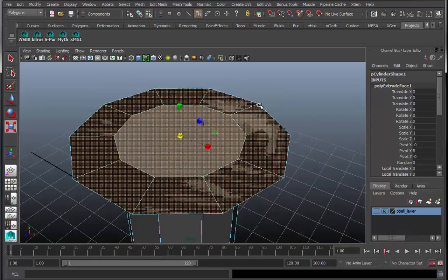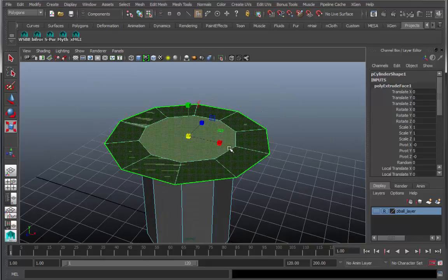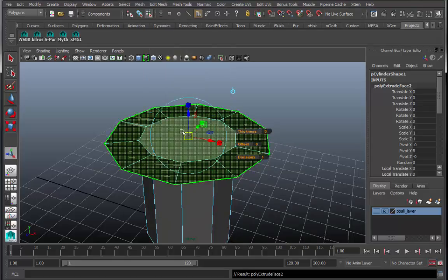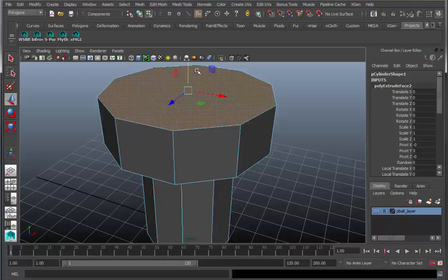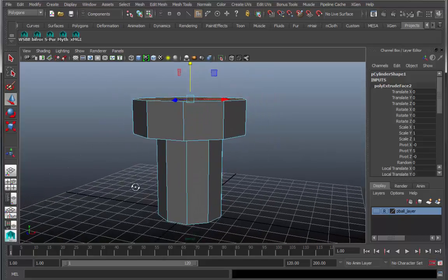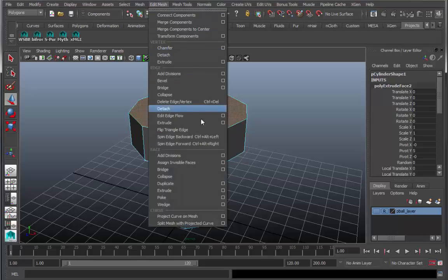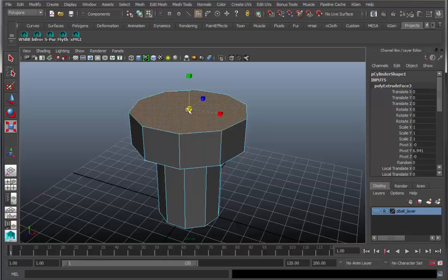Now, you're basically drawing one polygon right on top of another, but that's okay because we're going to continue extruding and separate them. Once again, come into Edit Mesh. Once again, go to Face Extrude, and now instead of the Scale tool, we're going to use the Move tool, and we're going to push things up. So now we're starting to make that little Mario tube. The last two steps are that you extrude yet again, and use the Scale tool now to bring things in.